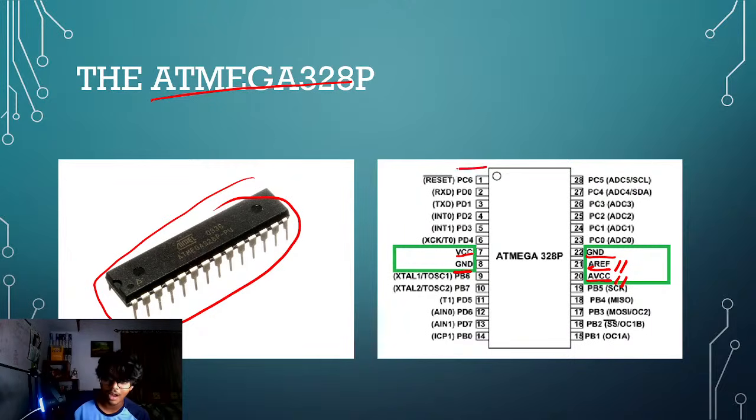Now every single other pin, okay, every single other pin, all of these pins are called GPIO pins, general purpose input output pins. So all of these have their own little flip flop attached to them. Okay, I'll tell you what exactly is attached to each pin, but there is some sort of memory attached to each pin, and it is capable of dynamically changing between input and output. Okay, so it can take an input and then it can give out output based on how you program it to work. Okay, is that clear? You guys have any questions?